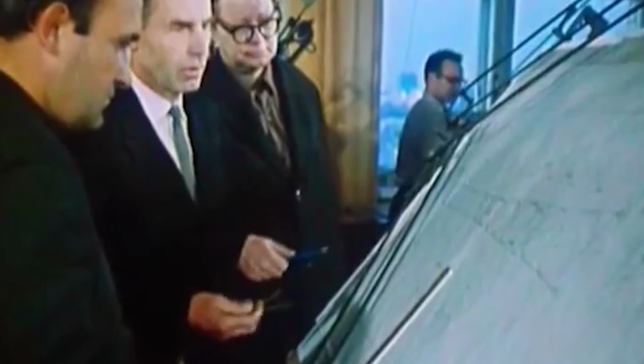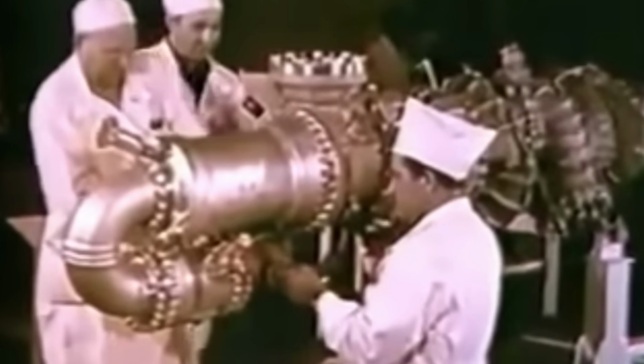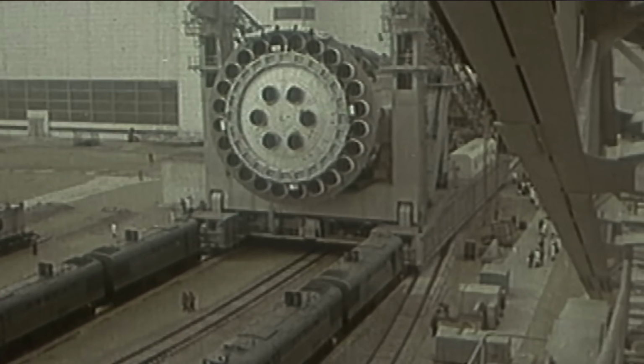The oxidizer-rich staged combustion cycle is very, very hard, since you're creating high-pressure, hot, gaseous oxygen, which sure loves to react with absolutely everything. It requires fancy metal alloys that can handle those extreme environments. The Soviets mastered this, as the majority of their engines were oxidizer-rich staged combustion cycle, including the NK-15 and NK-33s for the N1, the RD-170 on the Energia, and the RD-180 on the Atlas V. This is actually extremely difficult, and something the United States still hasn't achieved for an orbital rocket.